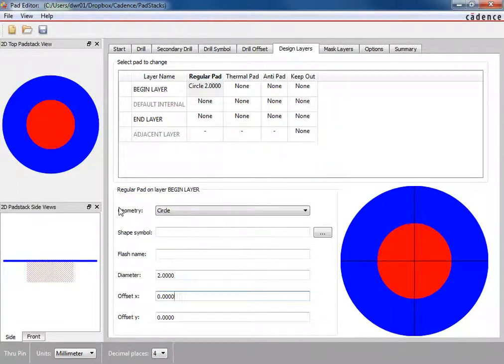You might say that's great, but we also have to be concerned that if you make that pad too big, the pins will run into each other when you create your footprint. That's where you need to refer to your CAD diagram for the size of pin and the amount of copper you can have. When we get into an example doing an actual footprint, we'll go into that in more detail. For now, I'm going to put this down to 1.5.